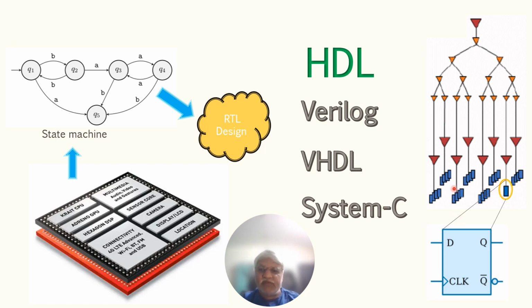These flip-flops again will have some combinatorial gates, and the result of the final combinatorial gate's logical operations will be stored again in another flip-flop. For example, if the clock triggers and the data starts from the flip-flop, it will go through a set of combinatorial gates and then be stored in this flip-flop, assume.